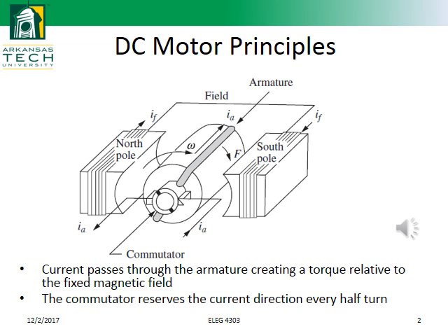The principle of a DC motor is whenever a current carrying conductor is placed in a magnetic field, it experiences a magnetic force. A stationary magnetic field is created either by permanent magnets or electromagnetic field. The current flows in a rotating circuit called an armature, which passes through the fixed field. The induced magnetic field in the armature is perpendicular to the fixed field. This creates a torque differential. The rotor turns due to the resulting torque.